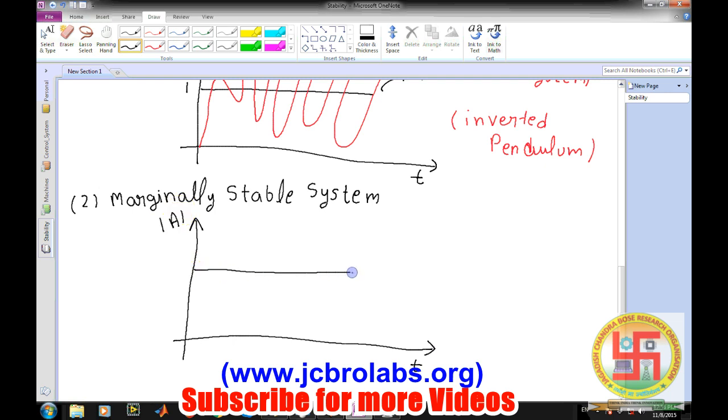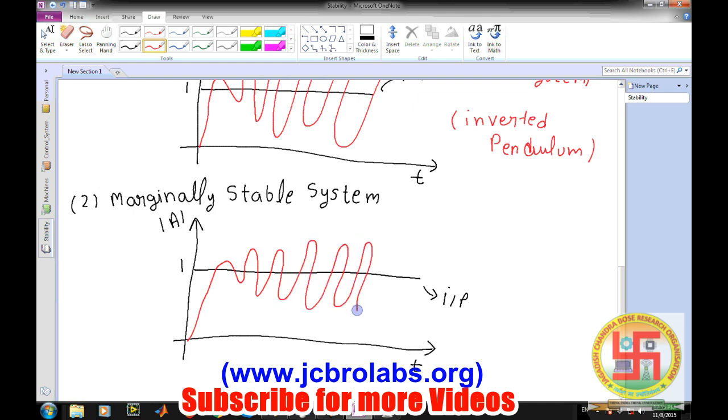This is the input signal and the maximum limit is 1. But the output goes like this and keeps on increasing, but as time tends to infinity it remains oscillating but stays within the limits. So the output is within these limits, say 1 plus mu and 1 minus mu. Then we say such a system is a marginally stable system.